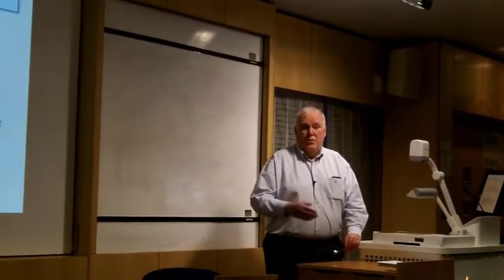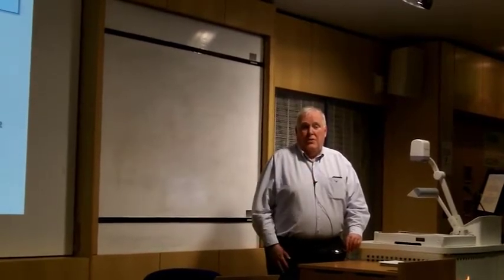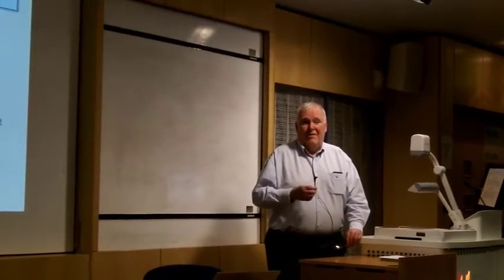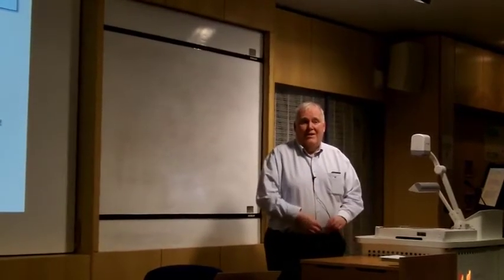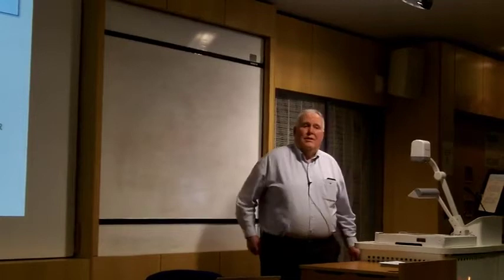So there's no restriction down to the second value. The trick is to make sure you get the right step time. That's what I was thinking. Yeah. Because in ordinary simulations, if you get the wrong step time, your simulation can be a load of rubbish.